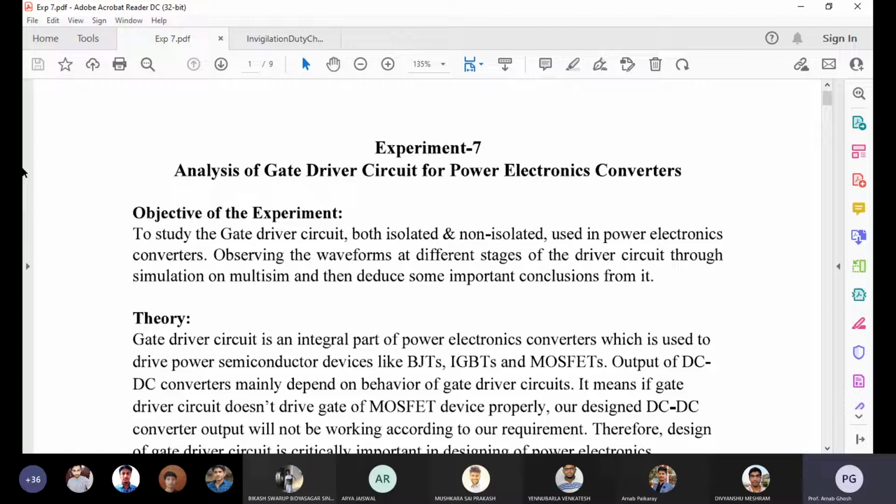In my measurement class I have also discussed how, suppose you are sensing one parameter, you compare that parameter with some reference value. After that, an error value is generated. That error passes through the compensator, or the controller, and the error is minimized by the controller, and you get some control signal. That control signal is slowly varying, so you can say it is an almost approximated DC value.